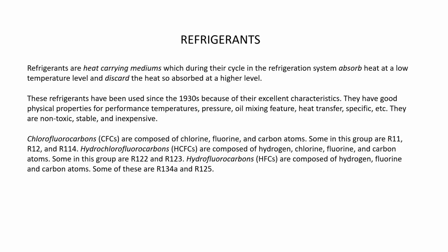So what are the refrigerants we can use? We call them CFCs, chlorofluorocarbons, which are composed of chlorine, fluorine and carbon atoms. This group includes R11, R12, R113, R114.